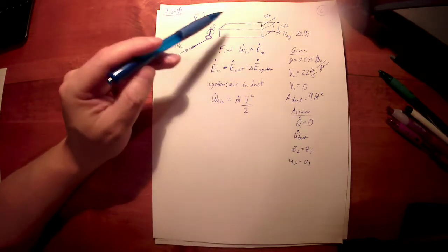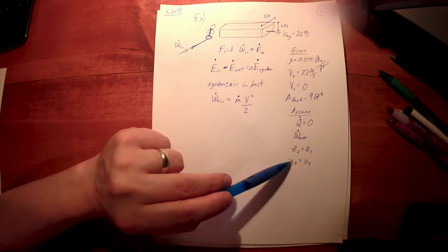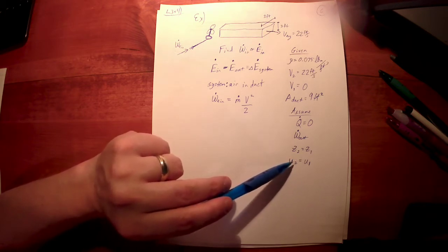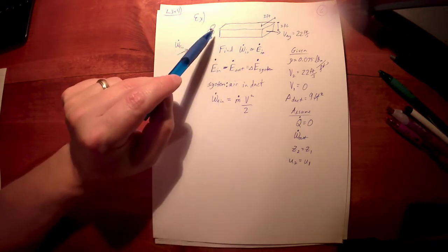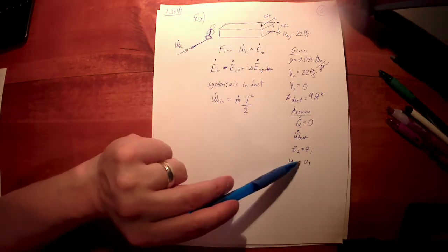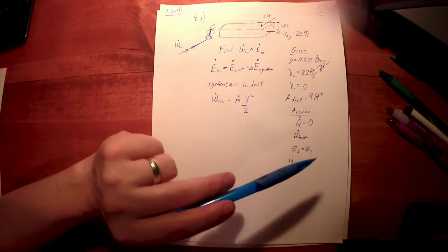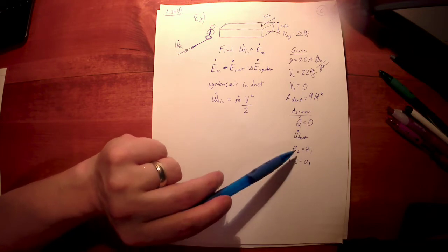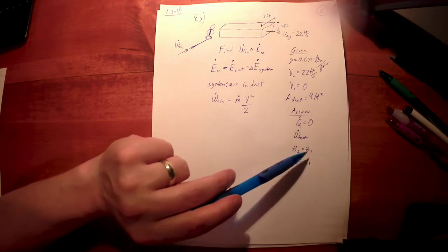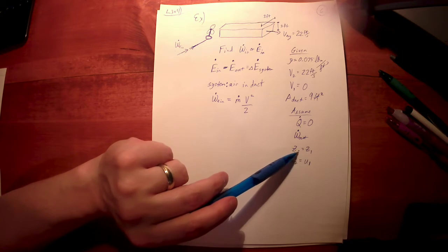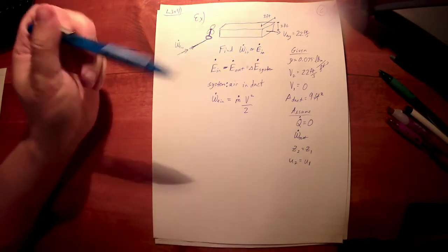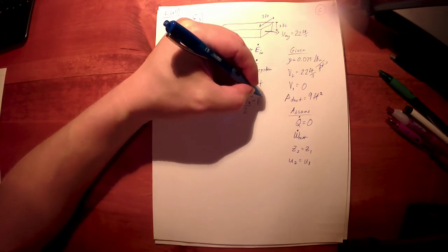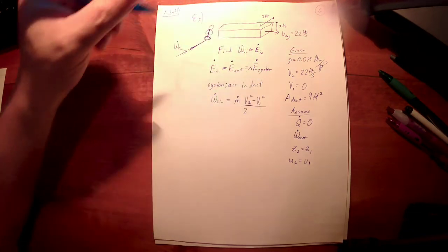Well, we don't know anything about the internal energy. That'll be chapter 3. So unless they're asking for the change in internal energy, realistically, I would need to know the temperature change from here to there to figure out the change in internal energy. We'll talk about that in chapters 3 and 4. But right now, we don't know that. So we're just going to have to make the assumption that this is the same. If they wanted you to deal with an elevation change, the change in potential energy, they would have given that to us. So we're just going to assume, and this is going to be V2. Right? You could say V2 squared minus V1 squared if you like. That's not going to hurt anything.